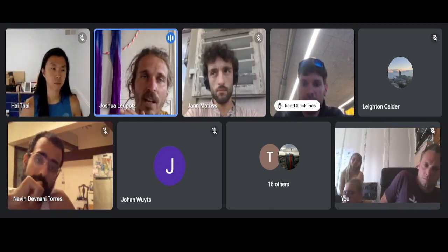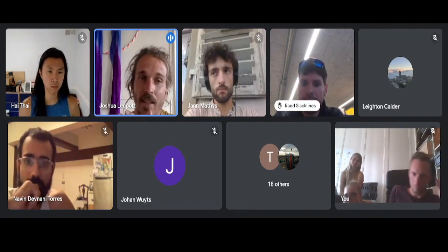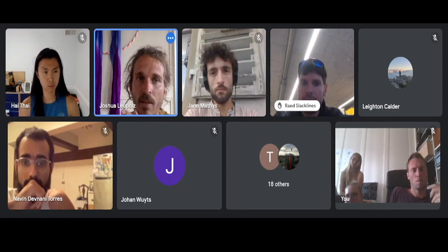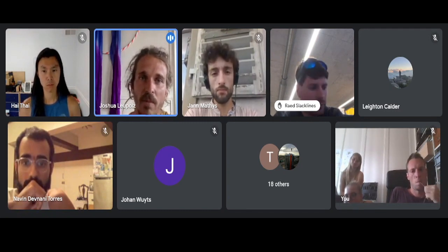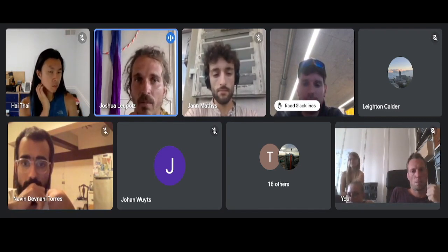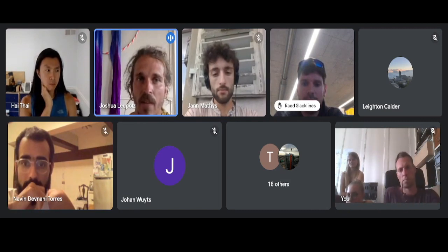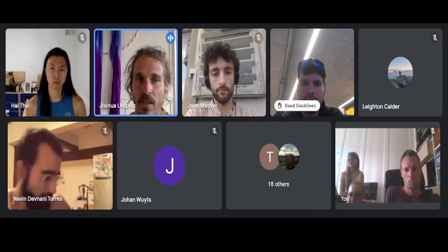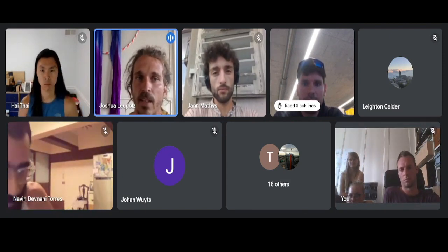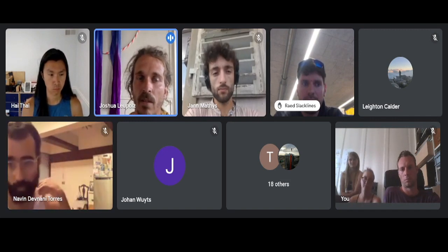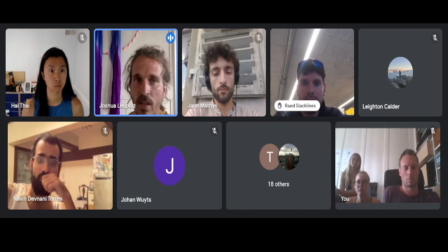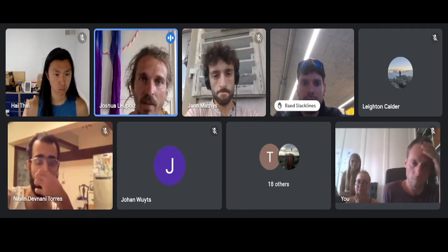And this is actually for backup falls, from what I did in the testing 3 years ago, just pulling relatively fast, that was actually relatively close to it, because in the beginning, apparently webbing is stretching out quite a bit more than you would expect from these graphs. And then later on it's recovering, it's the opposite. But yeah, for the bouncing and leash falls, there's definitely a big difference. There you can definitely see a really big difference if you pull it slowly, or if you have a line pre-tensioned to 2.5 kilonewton and then pull it to 5 kilonewton. There is really a big difference between what the stretch values give us and how it actually behaves.